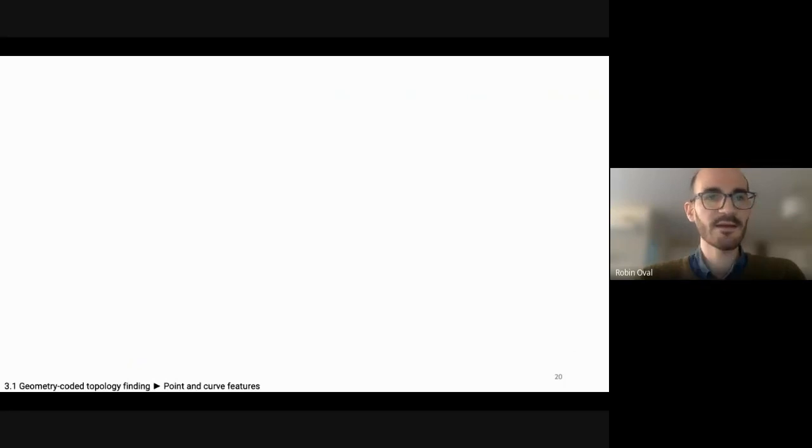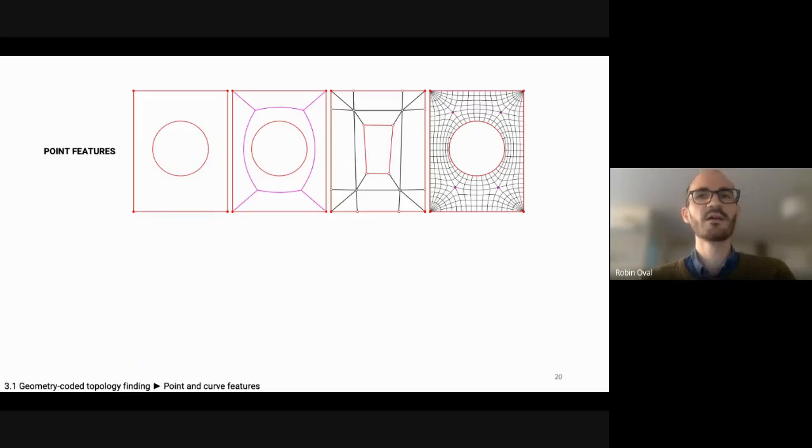So I handled the boundary of a surface, but I mentioned other aspects of heuristic features. So following a similar approach, one can include point features. So here in that case, I mentioned the fact that you have thrust only at the corners. So here there's this additional rule that will split the quad into two triangles, which are actually pseudo quads. So you can imagine it as a quad with a very short edge, where you have this point feature in order to form a pole point at the corner. And as such, you have this concentration of the forces at that location.